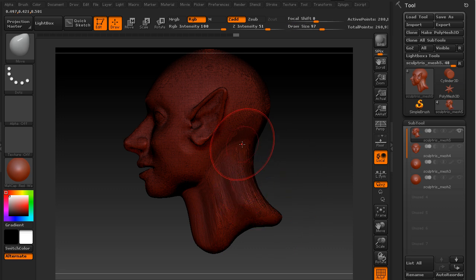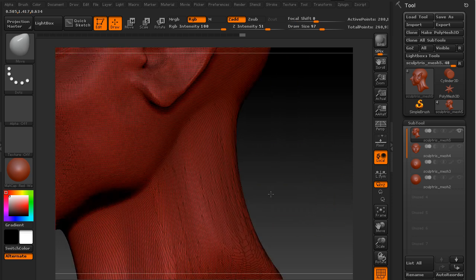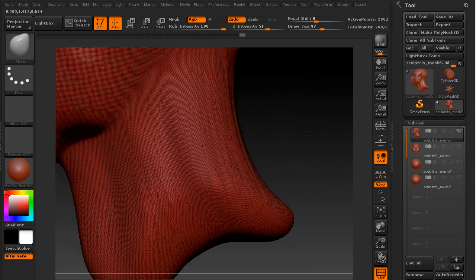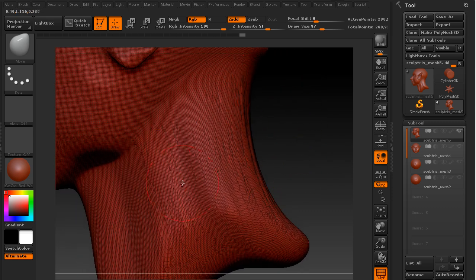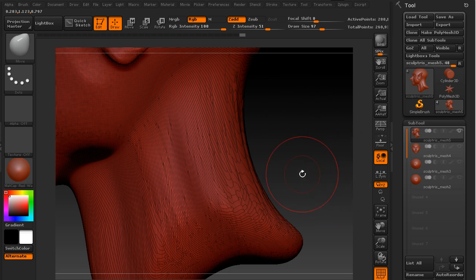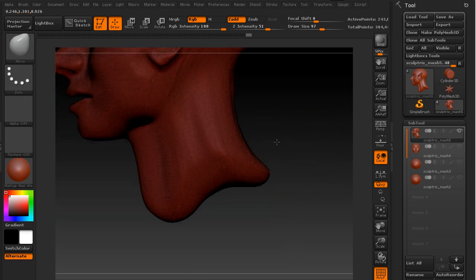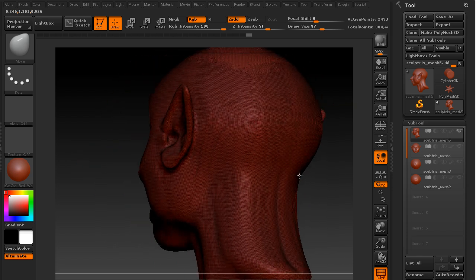And so now there we go, and we have all of these stretched out polygons, and you'll remember that in Sculptris these would be automatically converted into new polygons, but because this is ZBrush and we're using Dynamesh, it stretches out the polygons, and when you're happy with the overall shape, you drag a mask in empty space and then it remeshes. So it's sort of like Sculptris with that sort of polygon flow.